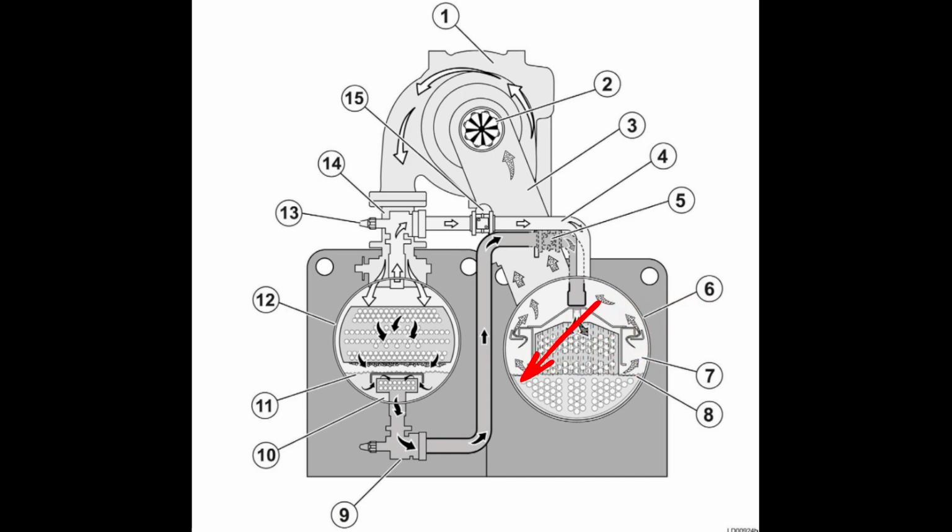But these eductor ports are designed to operate just below the top level of what that eductor was meant to draw in. And that's where the majority of our oil is expected to accumulate during operation. Just the bubbling action, it's going to bubble up and get to the top up here.